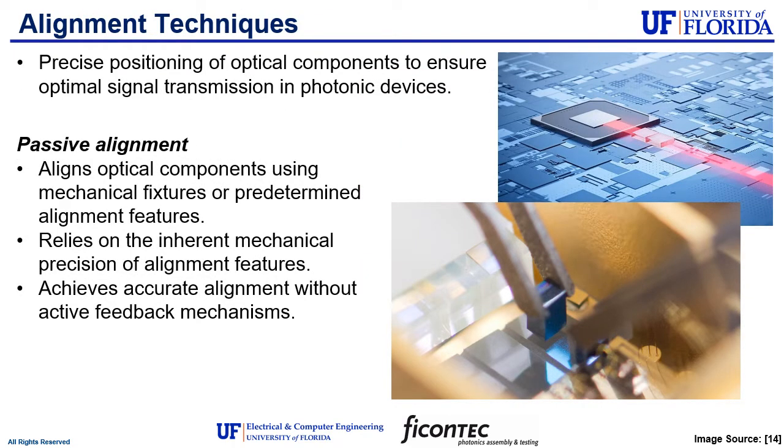Alignment of fiber optic cables and their respective transceiver modules is a crucial element of photonic devices that must be checked for. If not considered, alignment issues can lead to major inefficiencies or even a complete loss in signal. So it's important to ensure that fiber arrays are oriented directly in front of the PIC's receiving ports and that each optical cable is transmitting to the correct channel.